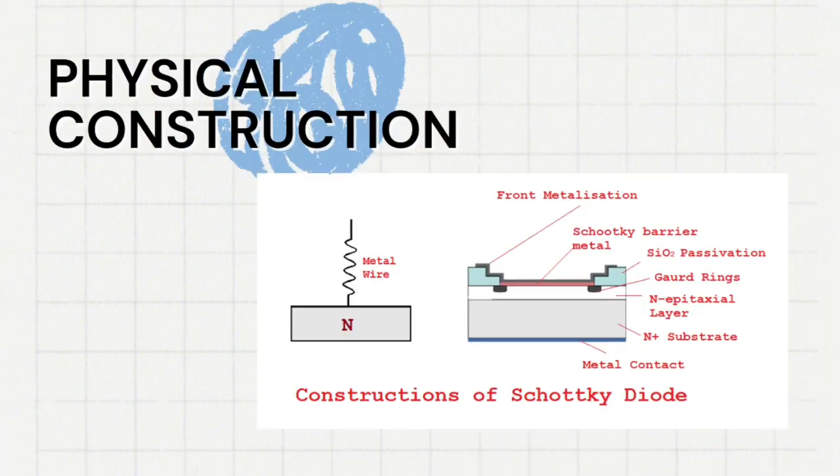An N-type semiconductor that has been mildly doped and a metal electrode are combined to create a Schottky diode. There is no depletion area in a Schottky diode because of the metal semiconductor junction. The device cannot function as a rectifier if the N-type material is not slightly doped.